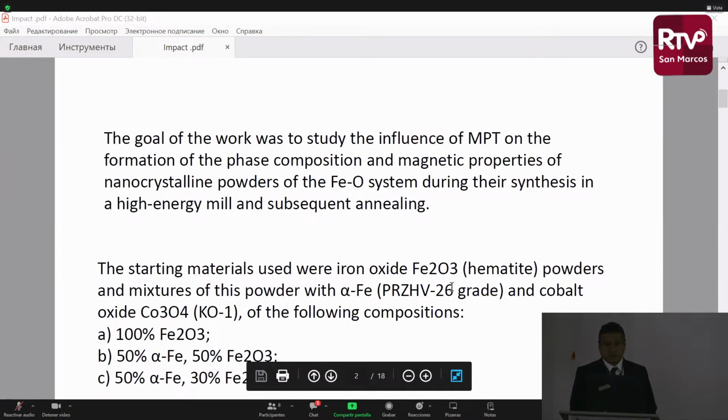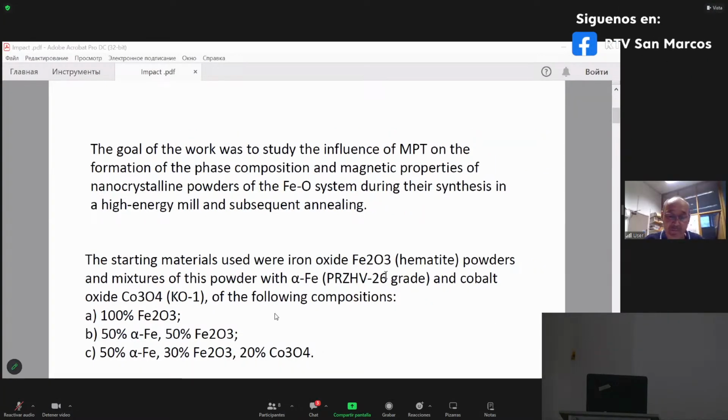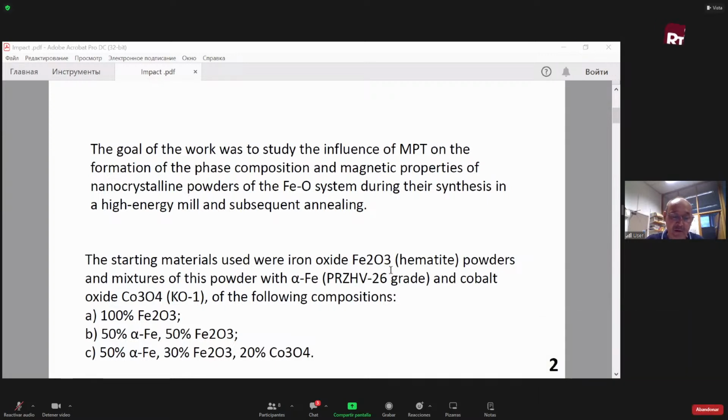As you know, magnetic pulse processing, which I will call MPT technology, is used in mining and processing industries before grinding in mills to soften the ore, or in the process of extracting a useful component. It is generally accepted that in a number of cases, MPT causes magnetostriction and piezostriction effects in grains of ore materials, characterized by the occurrence of deformations. As a result, tensile and shear stresses arise throughout the entire volume of ore and the grain boundaries.